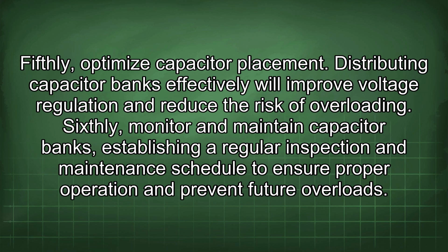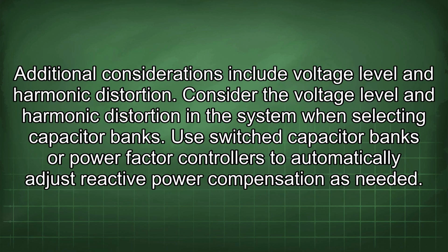Sixthly, monitor and maintain capacitor banks, establishing a regular inspection and maintenance schedule to ensure proper operation and prevent future overloads. Additional considerations include voltage level and harmonic distortion. Consider the voltage level and harmonic distortion in the system when selecting capacitor banks.